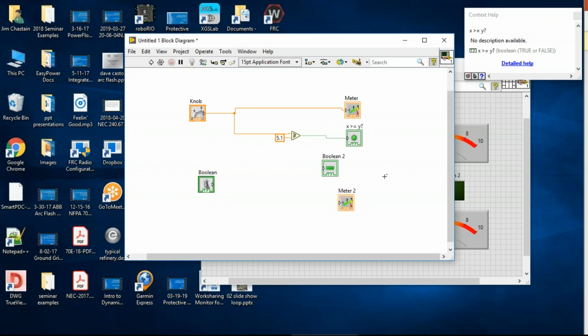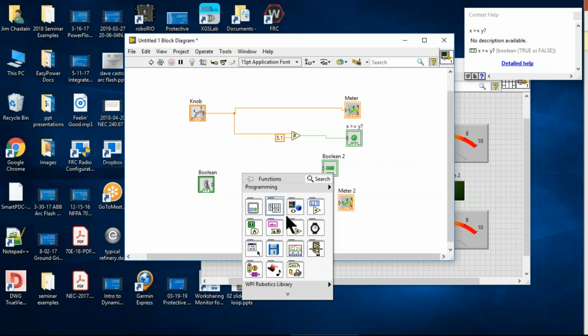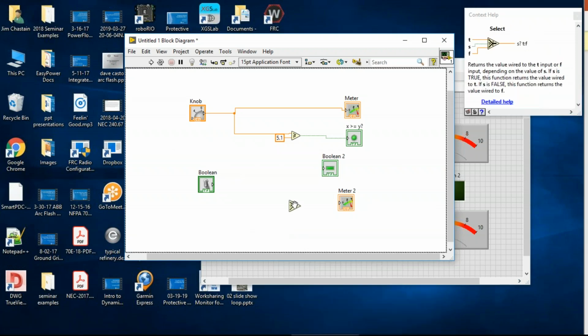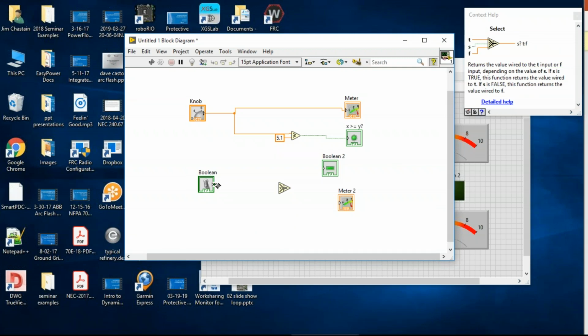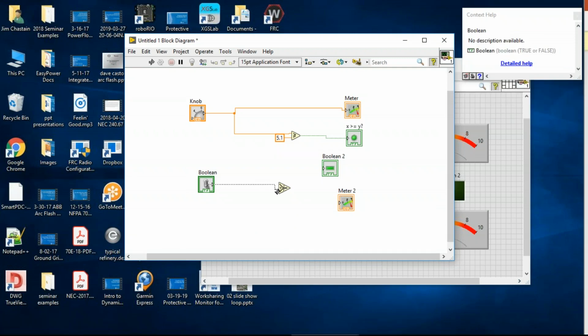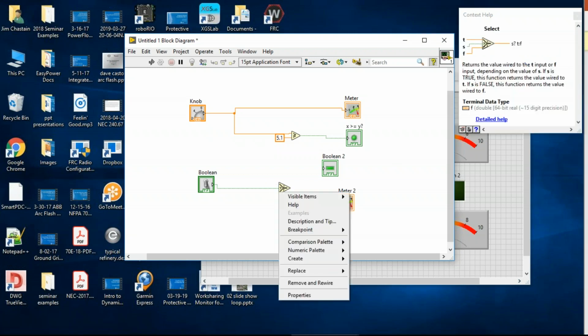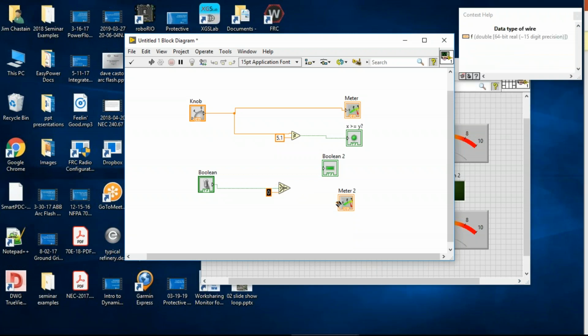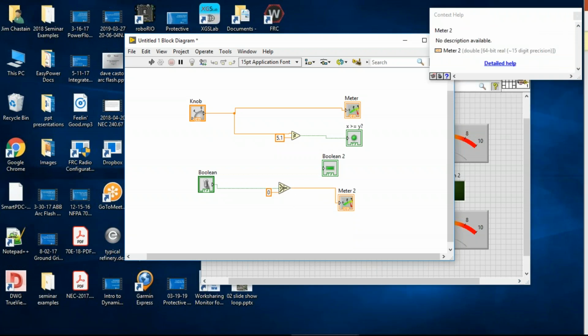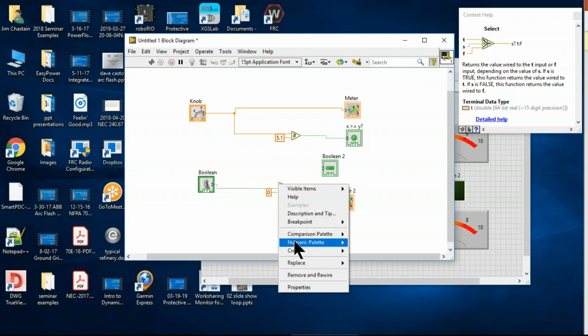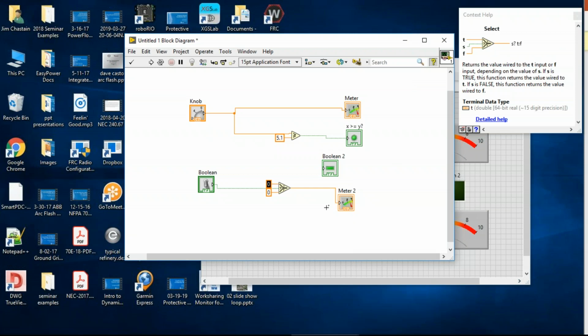All right. Now also I want to control on my Boolean palette. If I right click on the block diagram, go to the comparison palette, there's a selector switch. And this gives me the ability to control signals at the output with this input of a Boolean value. So Boolean is a digital, and my two outputs, when the Boolean signal is false, I want to have 0 displayed on the meter. When the Boolean input is true, I want to create a constant that shows 6.7.